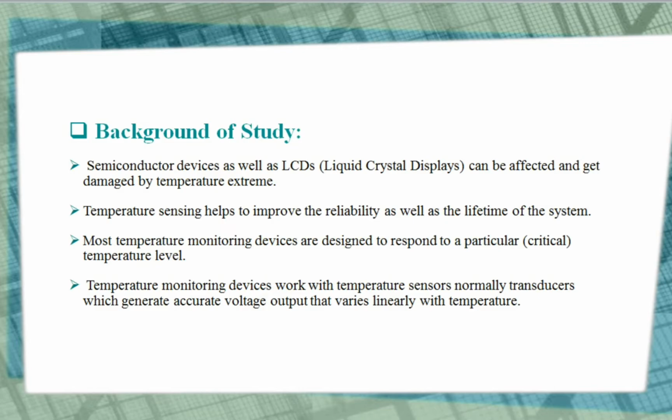They are mainly used for monitoring industrial machines, electric boilers, ovens, and other heat energy related activities, and this can be done by ensuring the temperature sensor and its leads are at the same temperature as the object to be measured. This usually involves making a good mechanical and thermal contact.